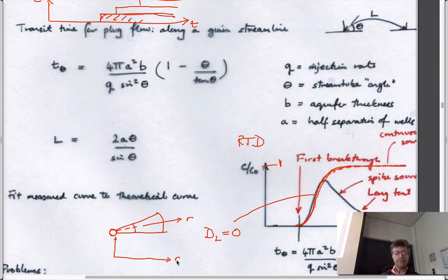It's going to be, for a given velocity here, it's going to be some magnitude. Once it flows out here, you have the same velocity, which is equal to a volumetric flow rate divided by a cross-sectional area. The cross-sectional area is getting bigger here, to here, to here. And so the velocity that starts out close to the well must drop as it goes outwards. So as you physically go out here, it starts off at a big velocity here, and there it ends up at a smaller velocity here.